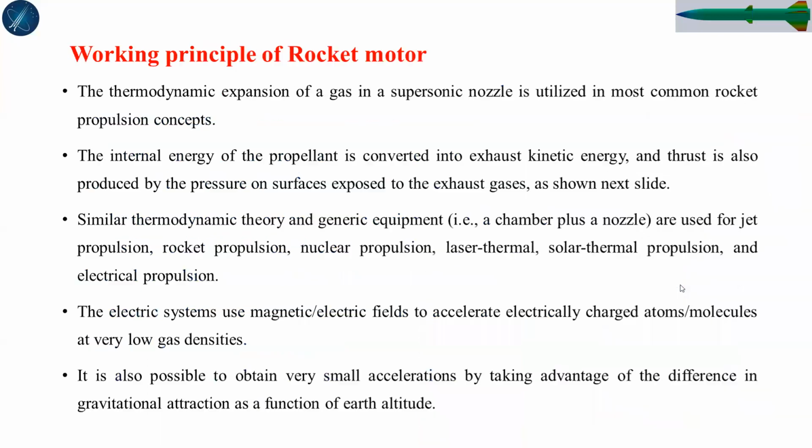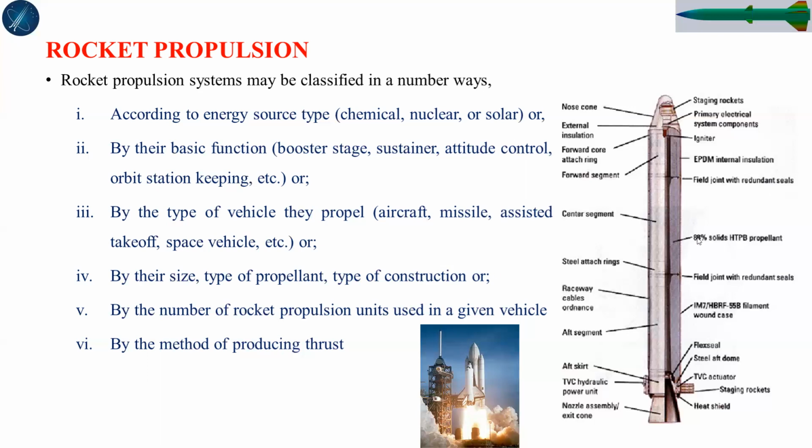So this is some constructional feature. 88% of the total mass is considered as propellant, not even more than 88. Only 12% is the construction of the important units of the rocket. The remainder is almost all propellant, because the major part of the rocket is propellant, in order to bring the given vehicle to the required destination, so we need more propellant than the structure itself.